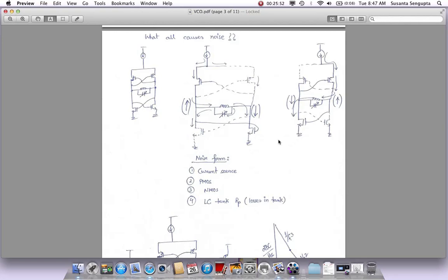And during that time, you have the current source, it just switches back to where this guy starts carrying more and more current. This guy carries less current now. It goes through the LC tank and comes over here. So if you look at the two cycles, we are adding noise in both the cycles. In the first cycle, we are adding noise from this guy that is showing up here, at the output. So these are the outputs. We have to see who is contributing what.